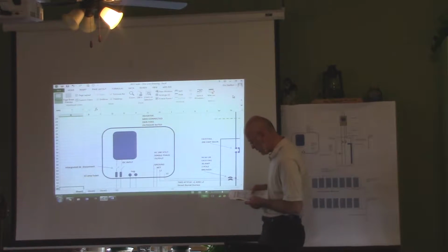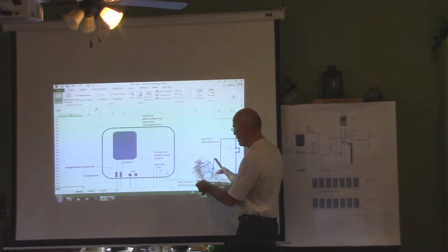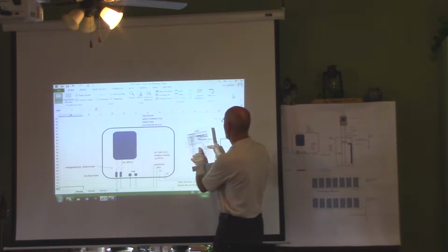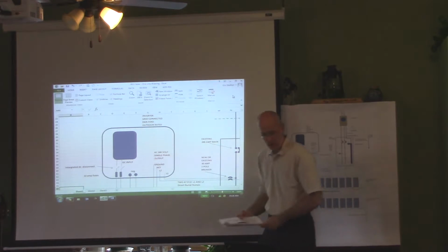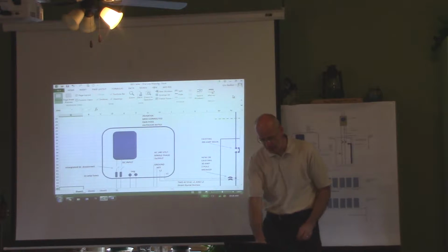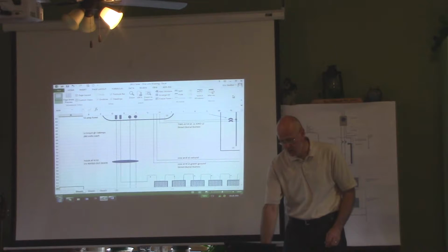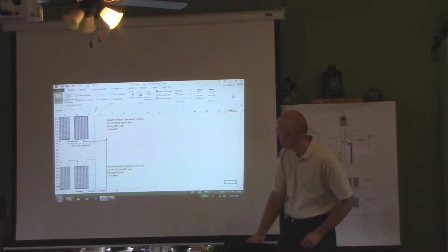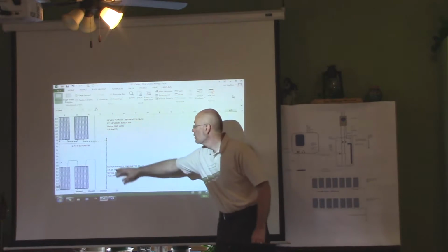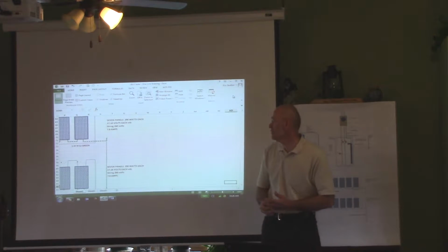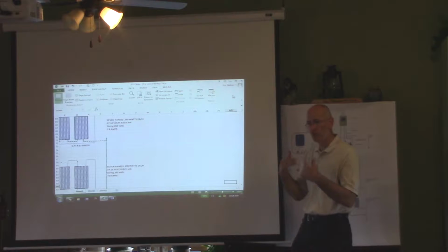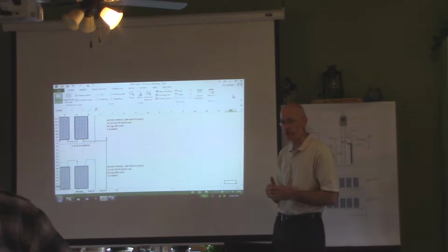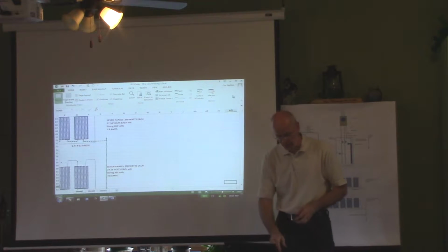There you go, maximum operating input current, 21 amps. About halfway down the page, maximum operating current on this model, 4.4, is 21 amps. And we're gonna give it 2 strings of 7 amps. So we'll be at 14, 15 amps, so we're below 21, so the inverter should be generally functional.